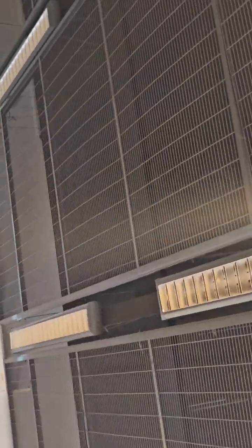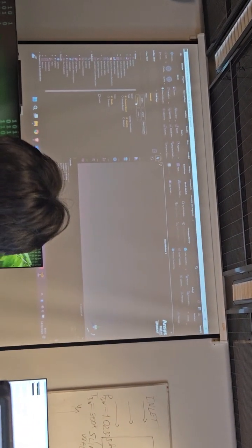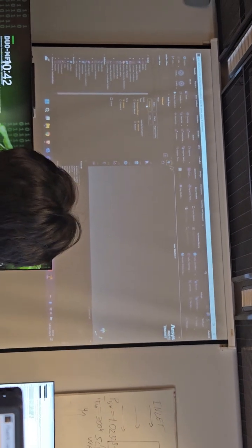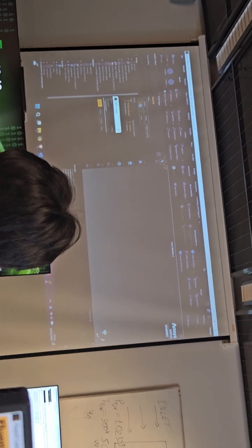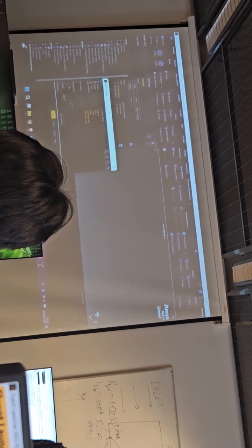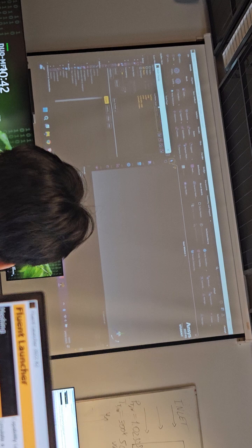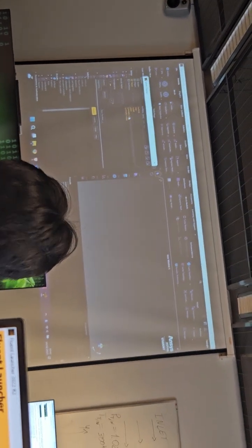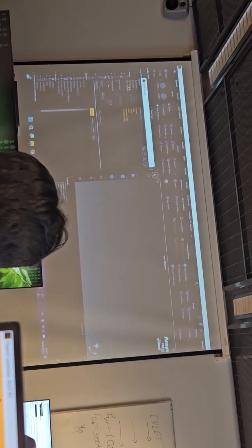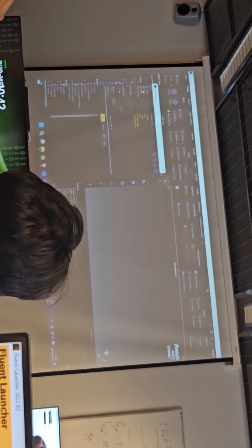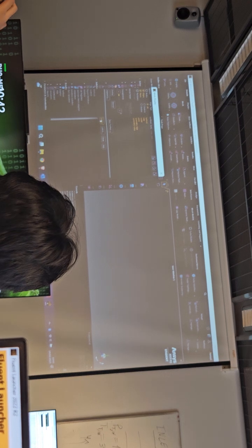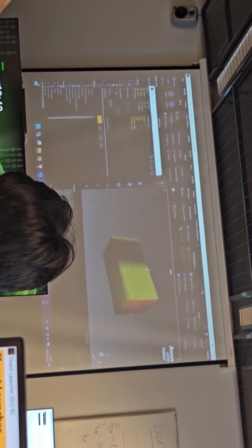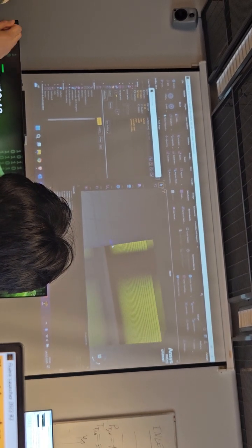And in this interface, now it's loaded, but you can also display it using this command over here in the general tab. It is display. You have the surfaces that you want to display, and then the options is faces. I will also plot the edges, so the grid, the mesh of the geometry, and display. So this is how it looks.